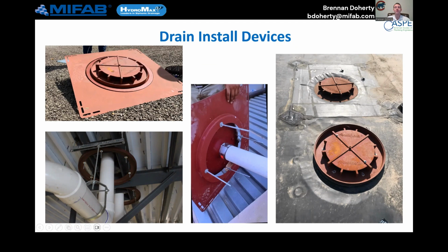And in the picture over here, we want these drains installed in line with the roof. This is a good install to me. What I basically mean by that is we don't want them to be sumped out in a 4x4 sump. We want it in line with the roof so it can grab water in every direction. Gravity drainage promotes water to the drain based on gravity force, pushing it to the drain. Siphonic, once it gets any thin layer of water, starts pulling water towards the drain in every direction.